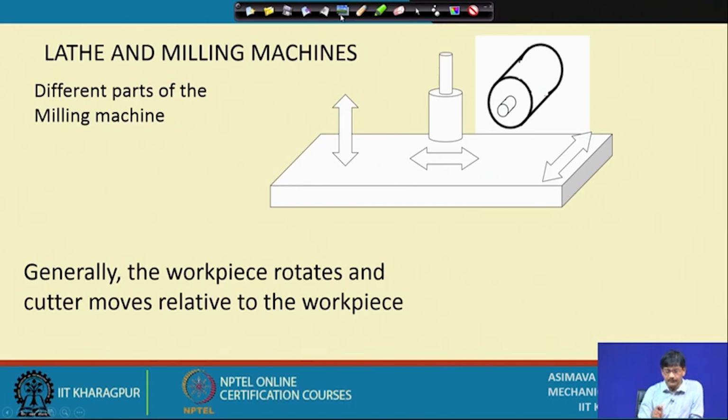Knee is basically, if we draw it here itself, comprising a vertical screw. When this vertical screw is rotated, the table, as a nut, moves up or down. So, this forms the basic support. If this be so, under the huge load of the whole machine table together with the workpiece weight, which can be to the tune of say 200 kgs, 250 kgs, the knee might buckle.